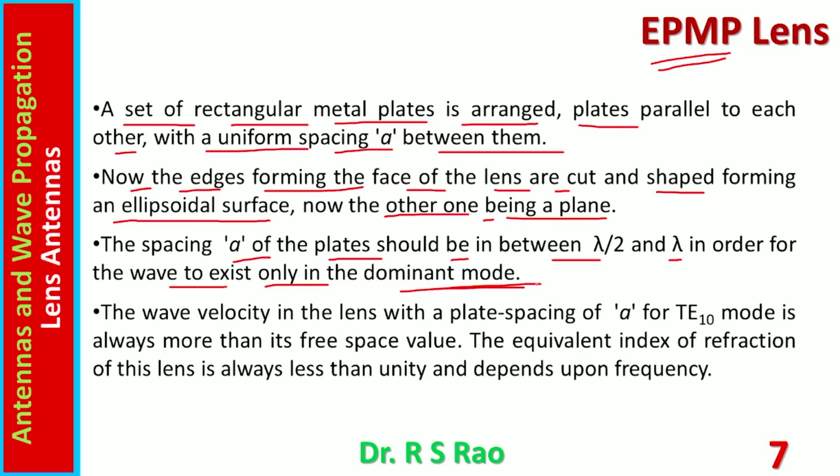When it is waveguide transmission, modes come into being. The dominant mode is used widely when waveguides are used for transmission. It is the simplest possible mode. Not only that, it is associated with the smallest cutoff frequency. So certain advantages are there. That's why most of the time dominant mode propagation is preferred in waveguides.